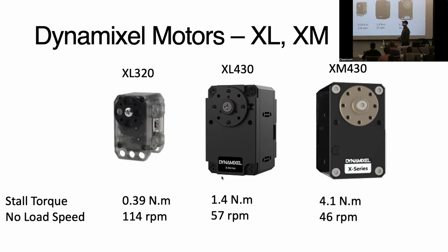But if the arm got into a mode that it got stuck and it had to be reset, students would have to reset it remotely and lose power to the arm, and the arm would just fall flat on the table. And we found that very, very quickly, the arms would destroy their wrist joints by crashing into the table. And so we replaced them with the higher torque metal motors, and that seems to have fixed the problem.